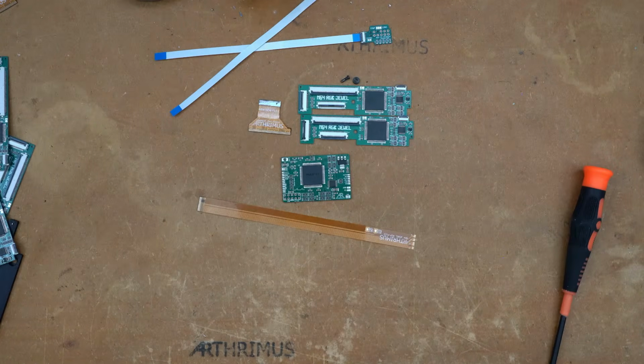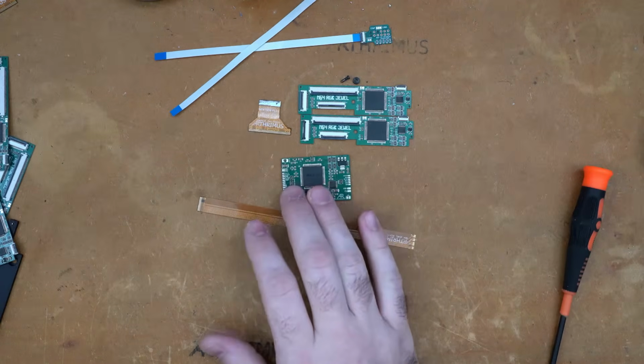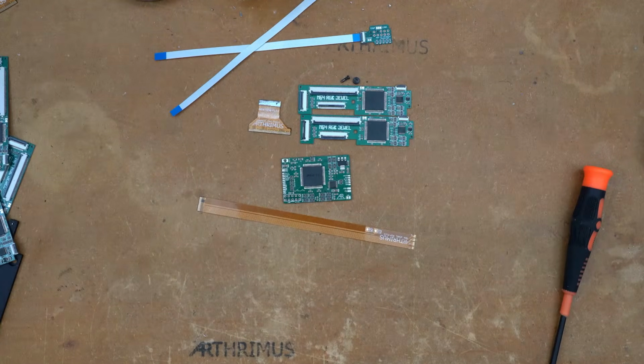So if you had really loud sounds happening in the audio channels, then you could see flickering on the screen. They solved that by integrating a separate 3.3 volt regulator to power the RGB boards that ran off of the 12 volt rail of the N64.